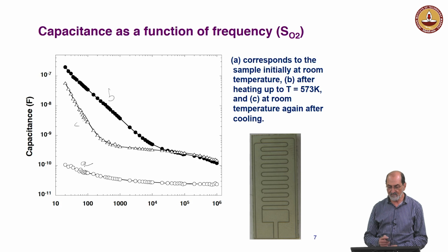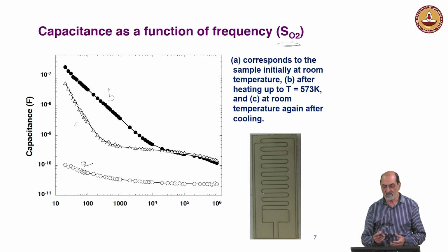Initially, we have this sample prepared under oxygen. We think that the depletion layers overlap, so the whole grain is depleted of carriers. Since it's completely depleted, the permittivity is that of the bulk. This is the permittivity I should find. We heat it up, and we found a different capacitance. Someone could say that something with the temperature is going on. Well, let's cool it down again under vacuum.